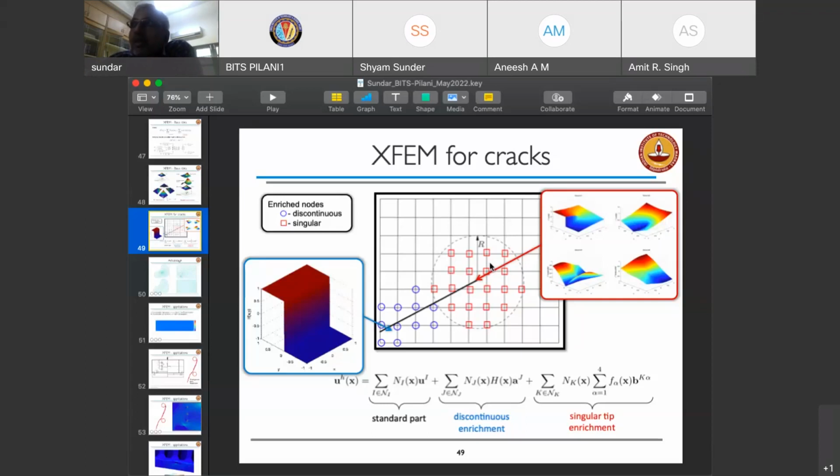I can probably share a small story. I happened to be on a review committee for an industry. They were trying to look at the fundamental frequency of a gearbox, right? They had done complex meshing, did everything in the analysis, and they said the first fundamental frequency is 0. That should immediately strike the person who did the analysis as wrong, because the casing, the gearbox, is completely fixed.